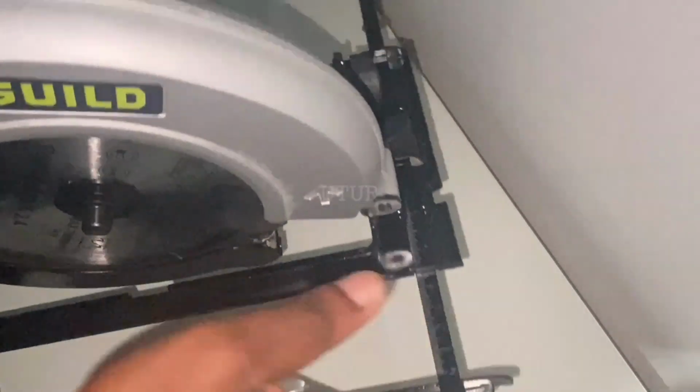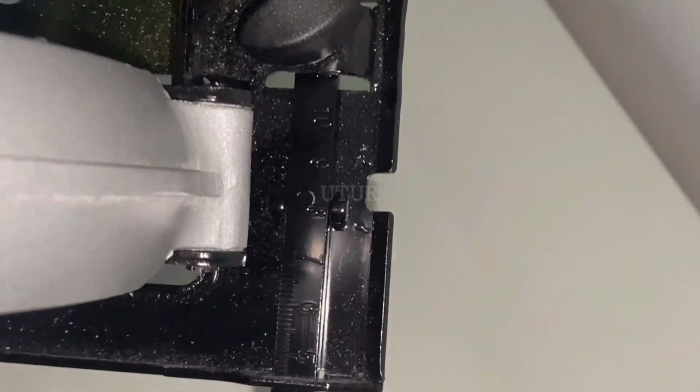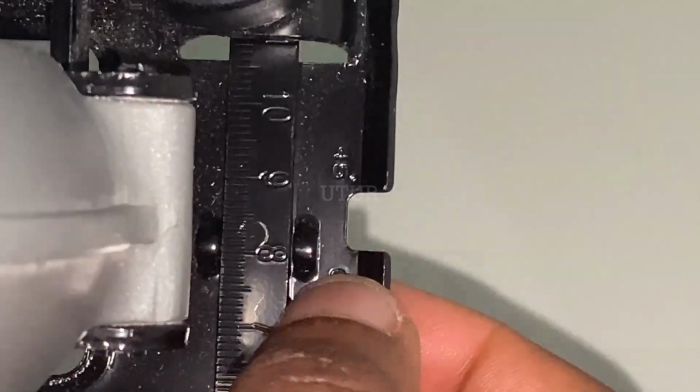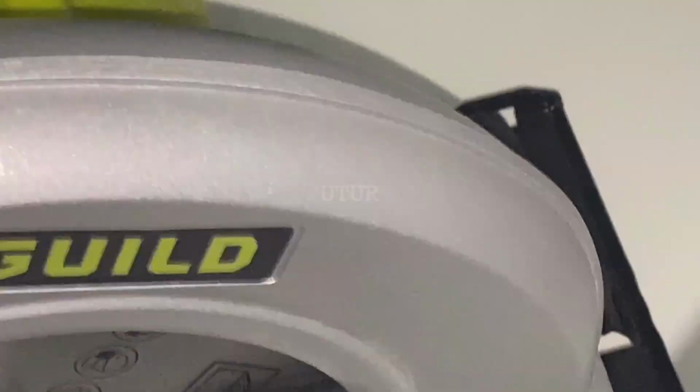The rip fence has also got a scale on it, which helps to determine the rip width. The rip fence has got an interchangeability capability, which essentially means that if you're cutting from the 9 o'clock position, which is to the left of the saw blade, you can undo the lock knob and swap the rip fence around to the left hand side of the saw blade, and then subsequently lock out the parallel guide and lock knob to key in the rip fence into position.